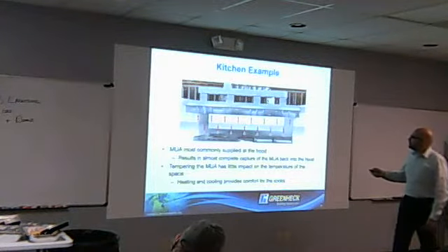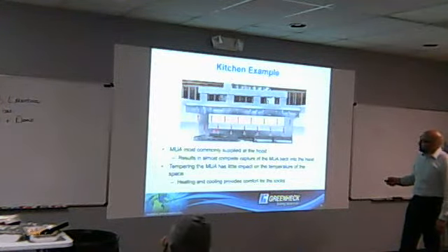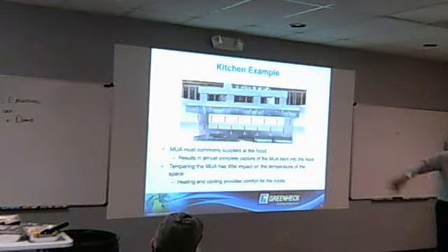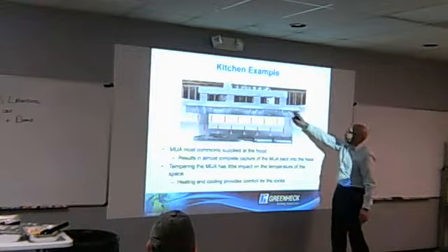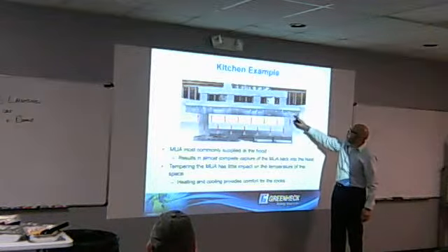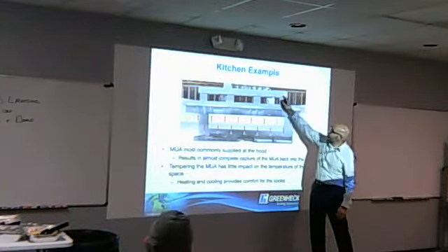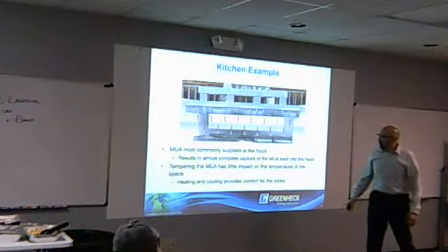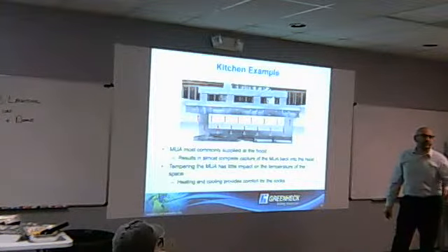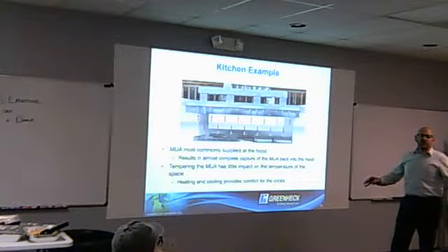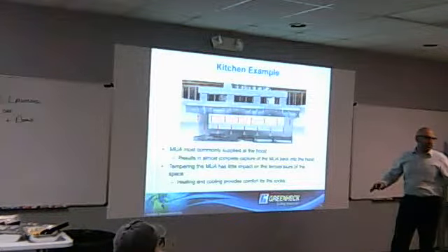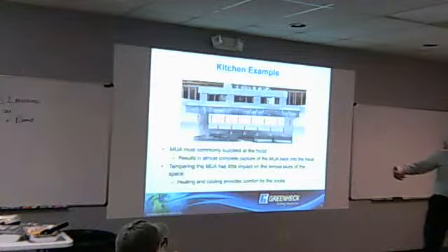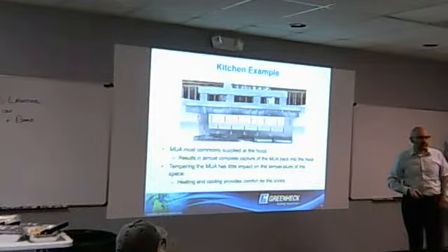In terms of kitchen hood, we try to show that because this makeup air is replacing what's being exhausted, there's no need to discharge it into the space, just keeping the air near the hood and letting it be pulled right out. So many times we'll have perimeter supply plenums around the hood. So if this is a hood, this is a perimeter supply plenum. This is from your makeup air, discharging air around the hood, just being exhausted out. There are some high-end restaurants where the chef says, I want my kitchen to be fully dehumidified, fully cooled, and we're conditioning, then you're probably going to bring that air further away, let it come in through the space, pick up every heat load, and then it's exhausted. But I don't see those very often.